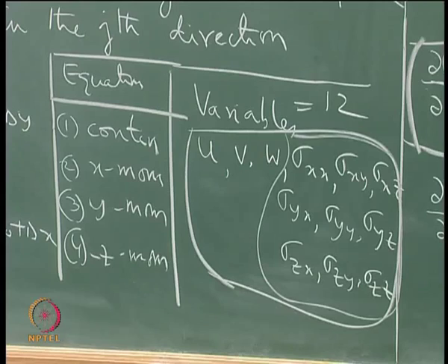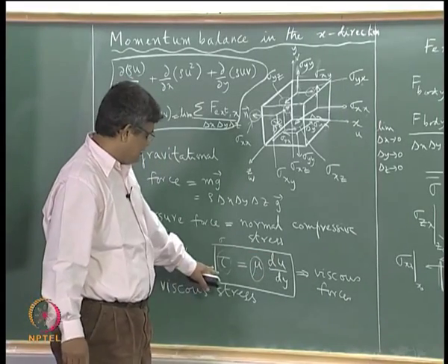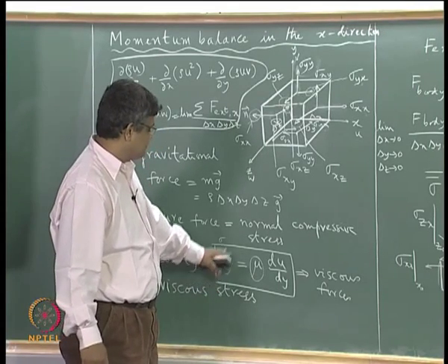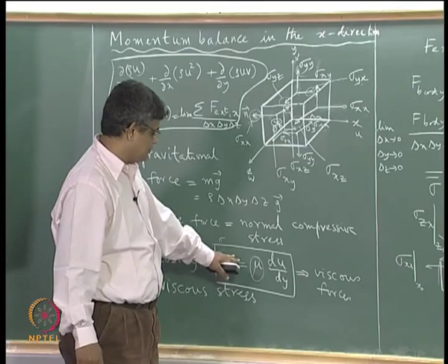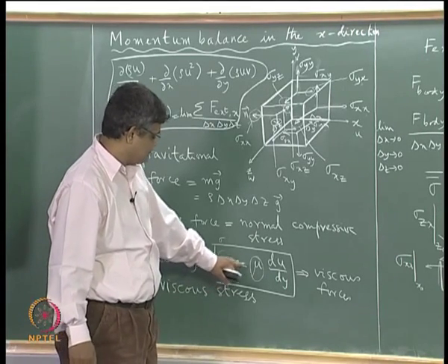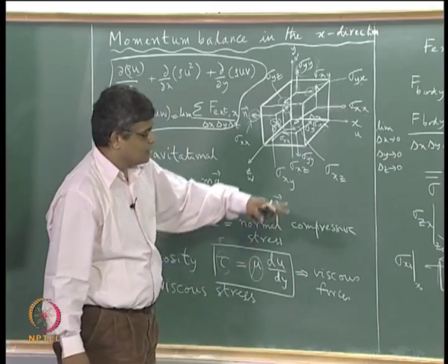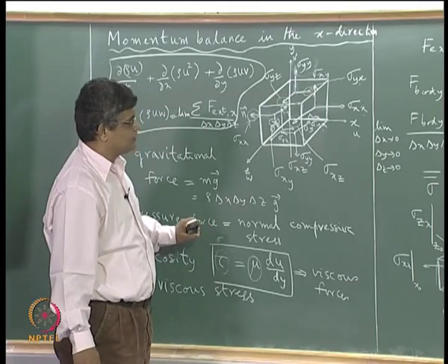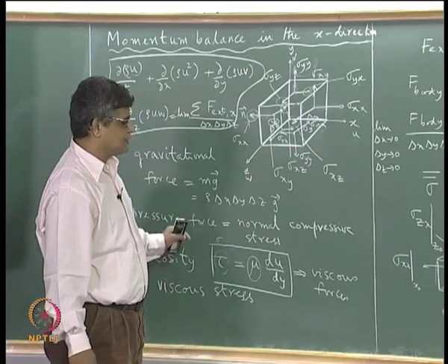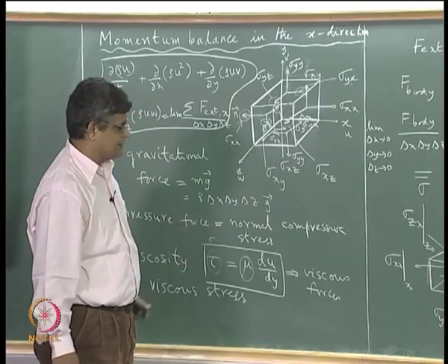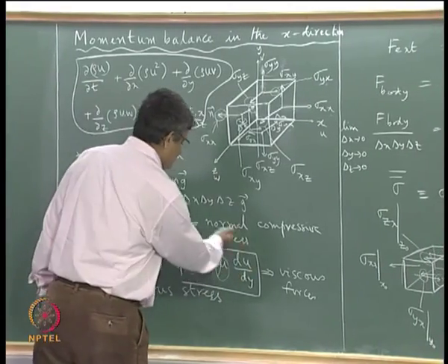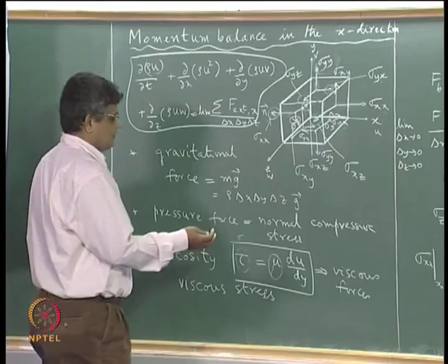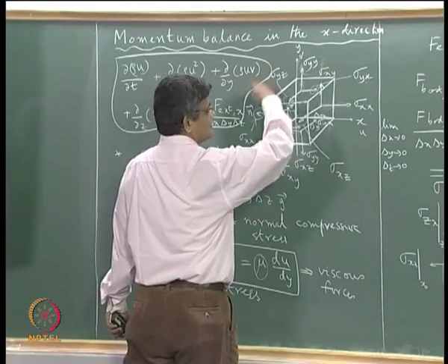We can go back to Newton's law and say, okay, we can replace this, but this is not enough for us, because what is the stress? This stress can be identified as tau xy or tau yx, something like that, but what about the other stresses? Okay, so this is for a specific case. This is for a specific case of one dimensional flow, where you have a single non-zero stress. In a general case, this particular relation is not valid. So we have to look for a more generic expression which is able to identify all the stress components in an equivalent way.